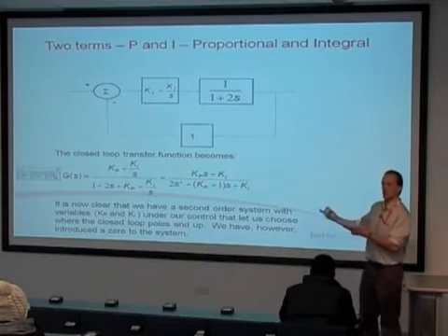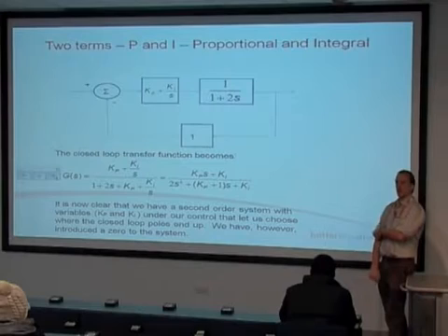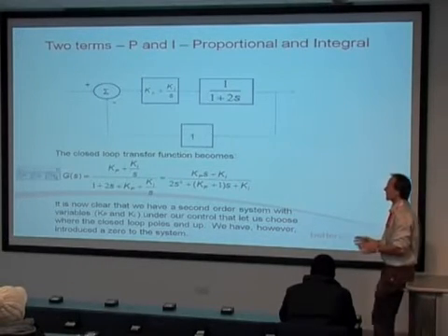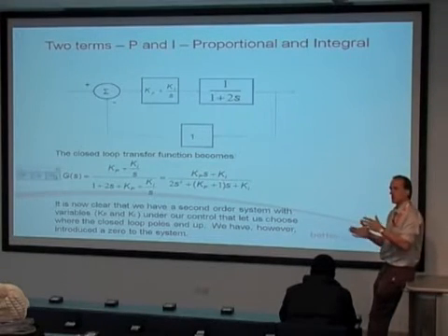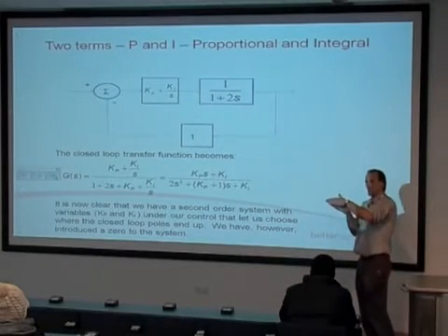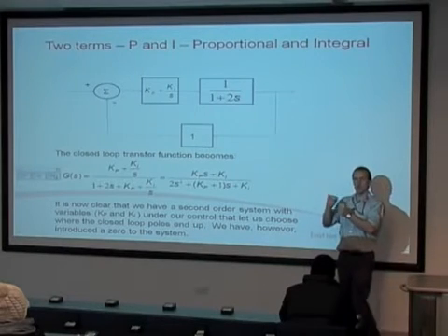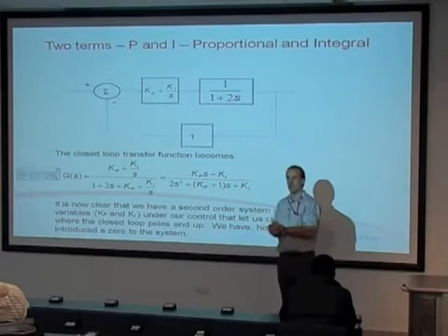Let's revert back to the example and ask yourself, what's the point of an integral control? One way to think about an integral control term: imagine you've got a system that's trying to control to 70 miles an hour, but it gets stuck at 69, and that error of 1 mile an hour too slow really isn't enough to force the throttle open far enough.